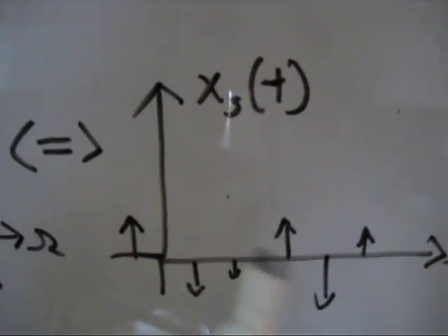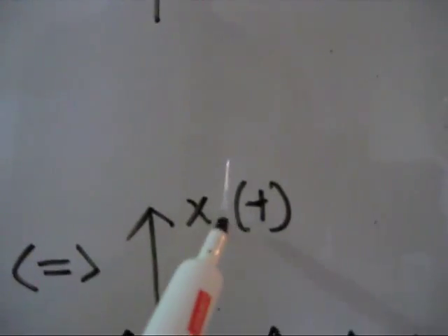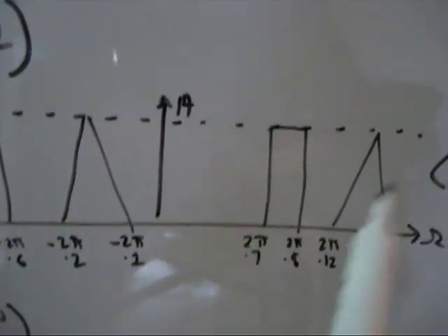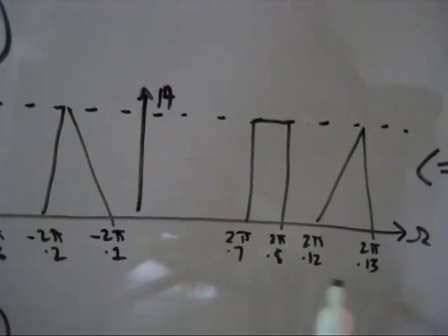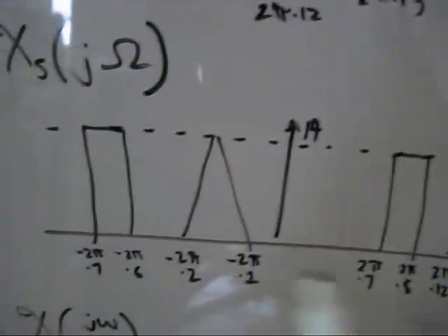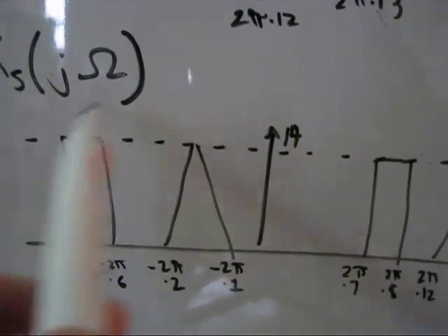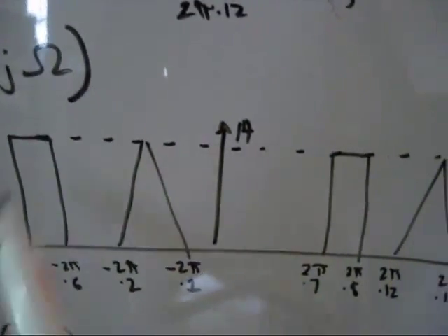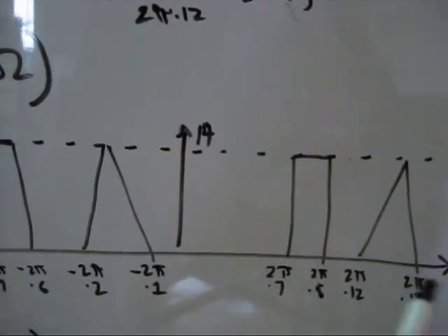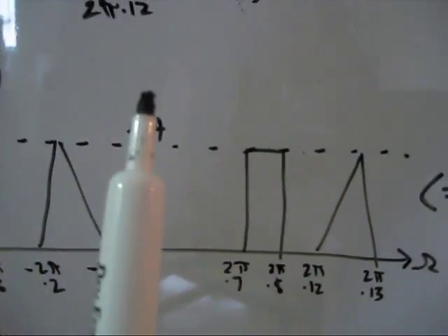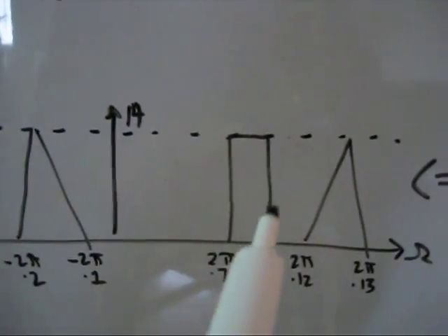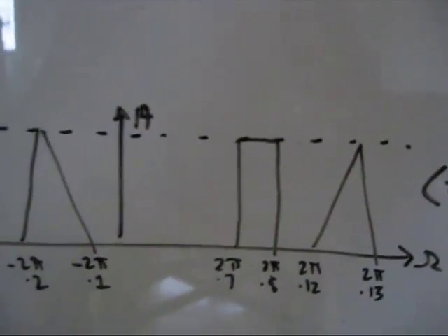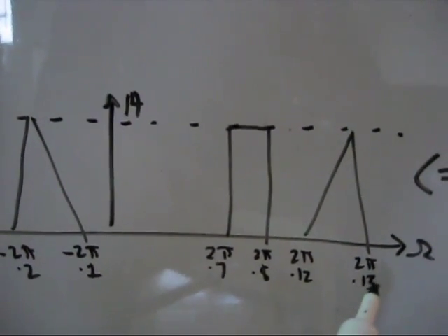It kind of looks like a sampled signal, and see, I did put an S. If we go over to the spectrum of it, notice now we have the original part here, 7 hertz, 8, 12, 13, but now we've got this component over here. Before we go any further, what I've done is sampled it at 14 hertz, not 26. That's the important part. We've sampled it at less than 2 times the highest frequency component.